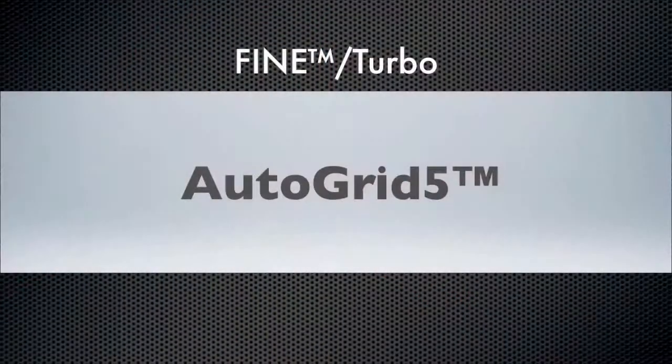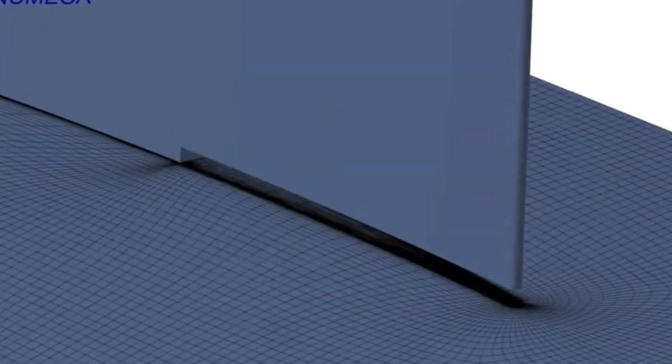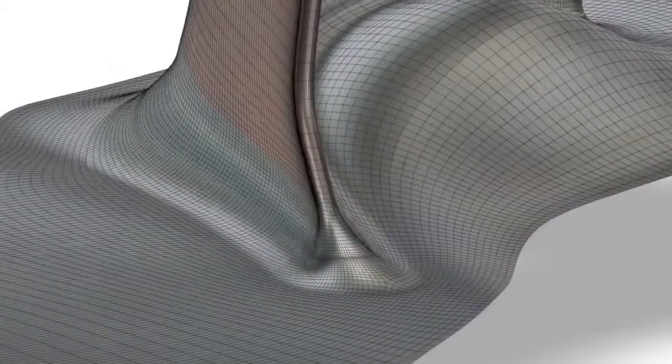In addition to the amazing multi-stage meshing capabilities of AutoGrid 5, automated structured meshing is pushed to new levels, allowing users to add complex details such as partial gaps, full fillet capture with butterfly topology, cooling and CHT meshing, non-axisymmetric end wall treatments, and more.